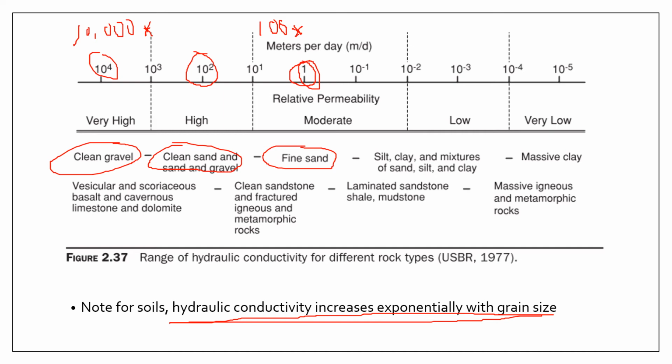Soil types can give you very unreliable estimates for hydraulic conductivity. Most of the time, laboratory testing in hydrogeology is just supporting, auxiliary data. We always rely on in situ testing.